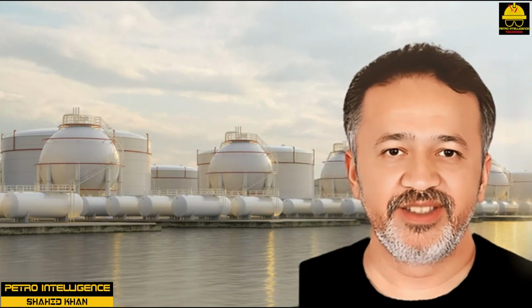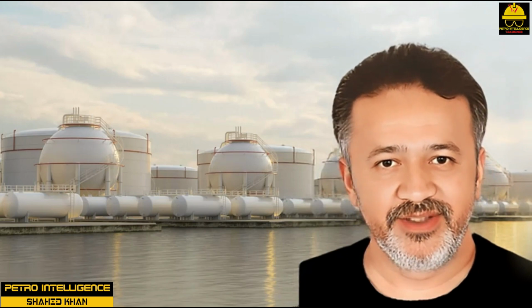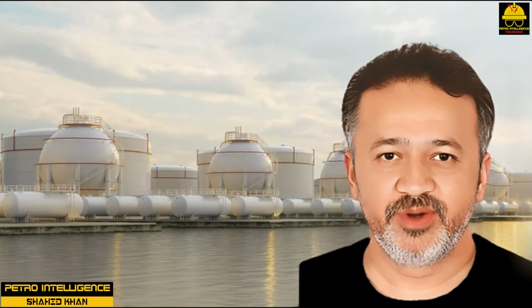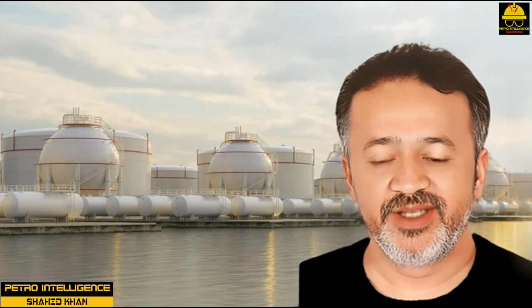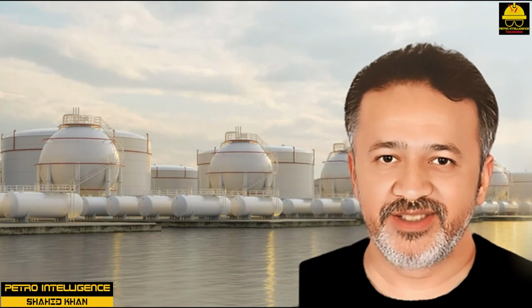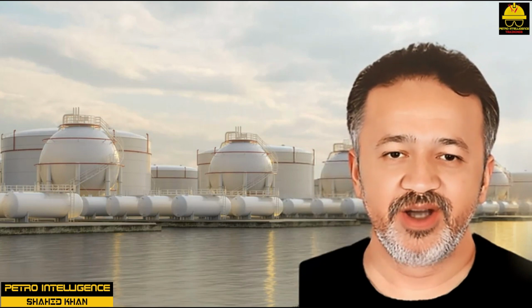Tanks can be divided into 4 general categories: atmospheric tanks, low-pressure tanks, 0 to 2.5 psig, medium-pressure tanks, 2.5 to 15 psig, and high-pressure tanks, above 15 psig. Depending on the vapor pressure and temperature of the stock in an atmospheric tank, the vapor space may be filled with varying mixtures of vapor and air.